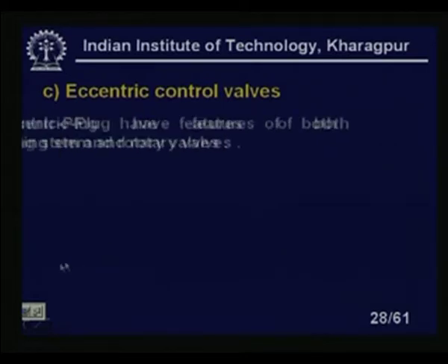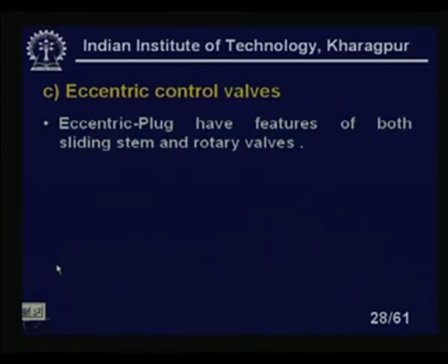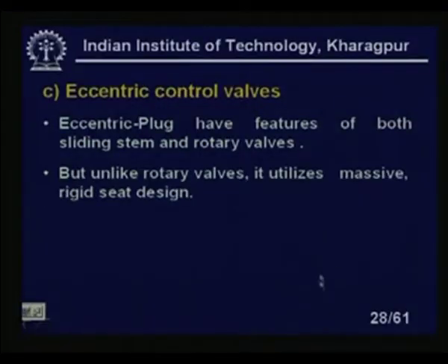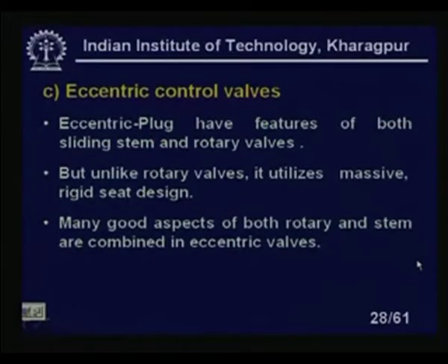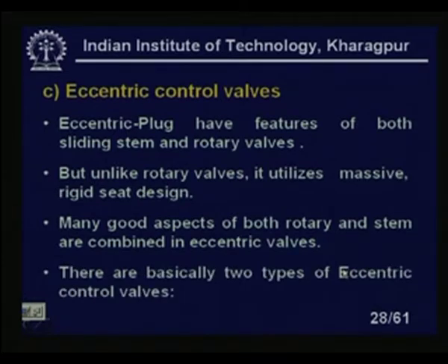Eccentric control valves. Eccentric plug valves have features of both the sliding stem and rotary valves. Okay, there are features of the rotary valves as well as sliding stem valves, but unlike rotary valves, it utilizes a massive rigid seat design. Seat design should be very rigid here. So, many good aspects of both rotary and stem are combined in the eccentric valve, right. So, both the combinations are there. So, obviously, in some applications this is very stringent.